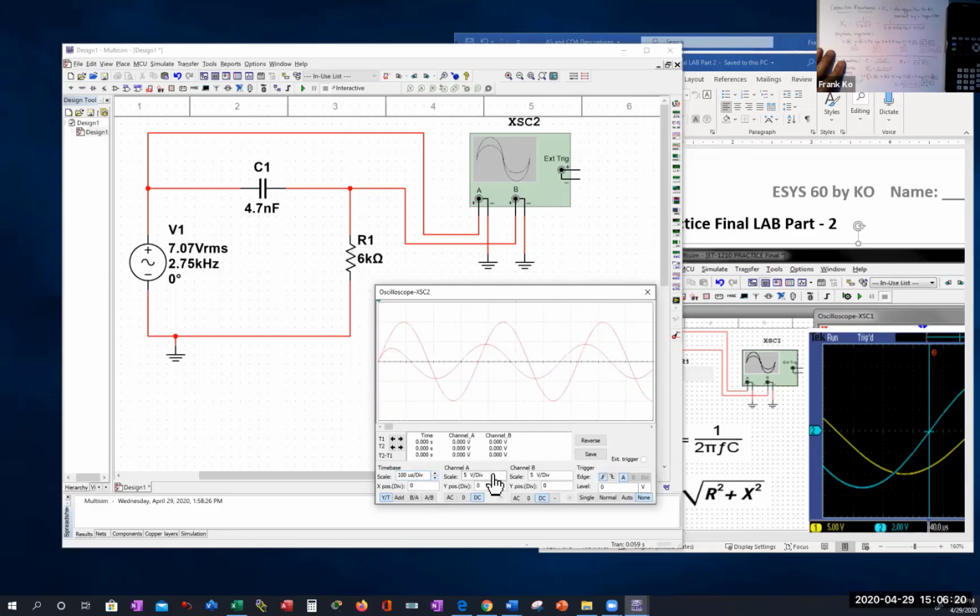After you ascertain that the voltage is 5 volts, 5 volts, then you bring in the cursors. You come up here, grab one of these lines, right there. Here's one, move that to a point, grab the next one, move that to another point, and the time in between, somewhere between 67 to 68 microseconds, okay?